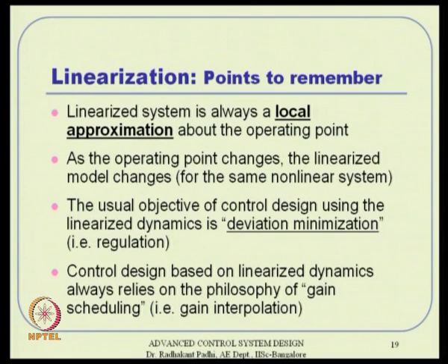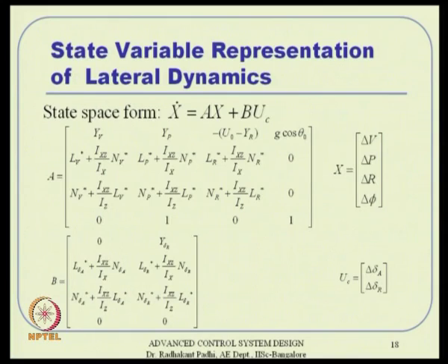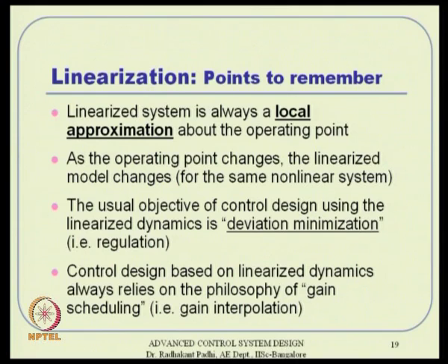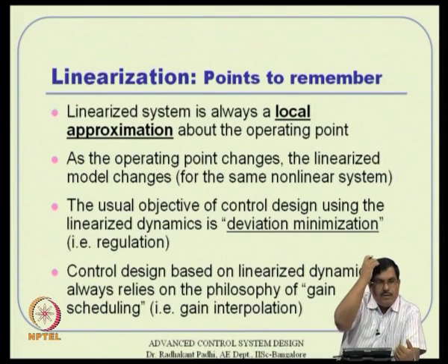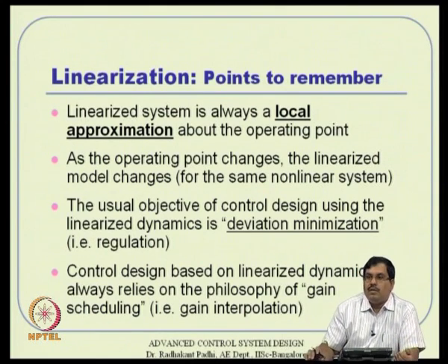For example, in rocket dynamics, as the rocket flies, a large amount of mass comes out. So, thrust is also a function of time, as well as the mass of the vehicle, and hence the moment of inertia, because the mass is gone. The Cg also keeps on travelling, because Cg is a point about which the net moment is 0.